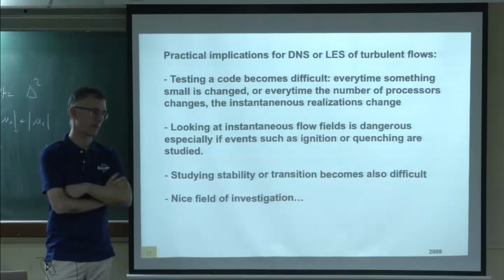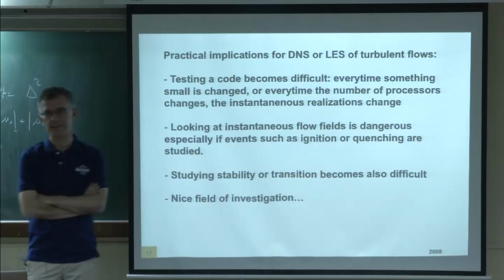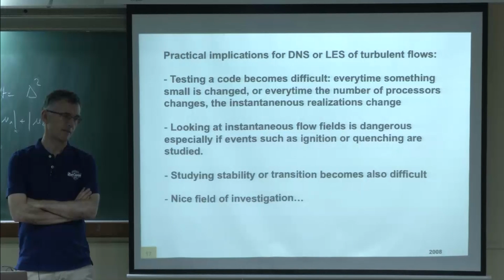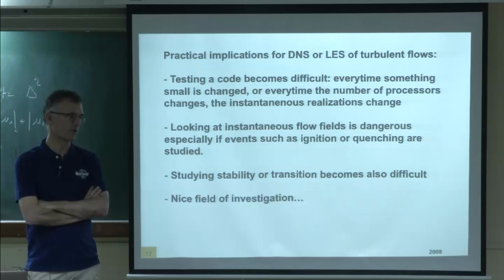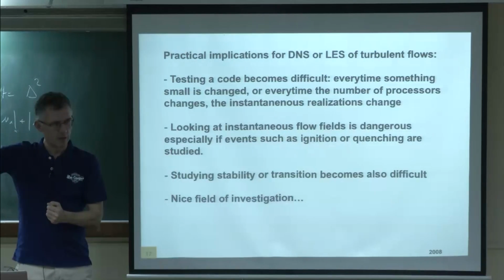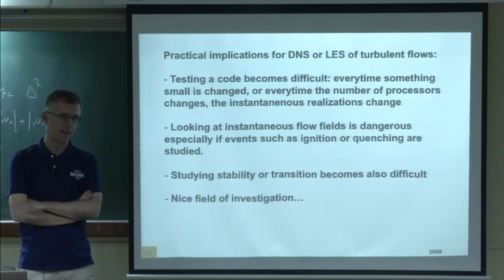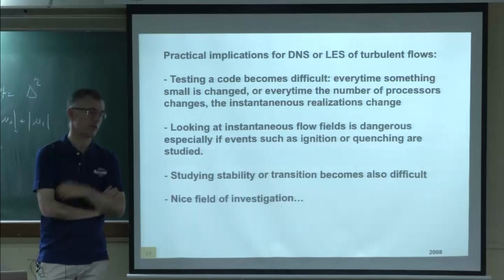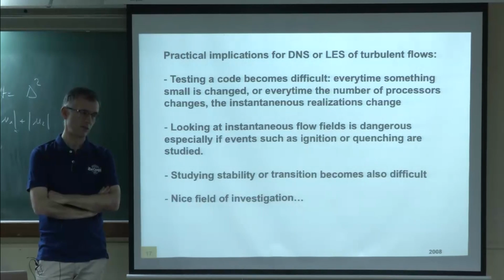So what do I trust then? The low number of cores because it has low rounding errors? That's difficult to say. Ideally you run it on one core and you don't have any such interfaces which give you rounding errors. That is the ideal solution. There's no good answer to that. I would say the first thing really is to increase the number of cycles that you do, and normally this would average the rounding errors. If you run too many cycles, you get to a steady harmonic situation that should work. It shouldn't make a big difference.